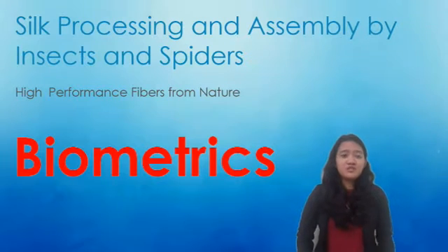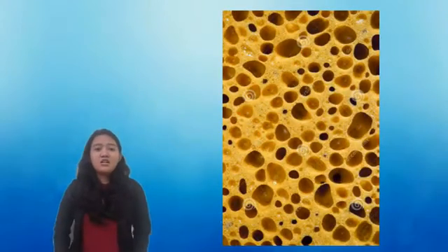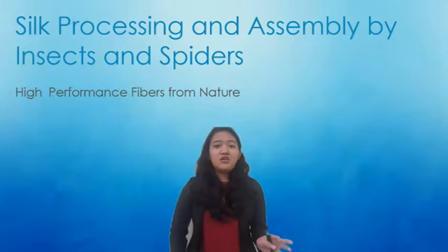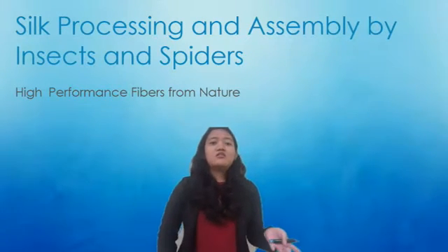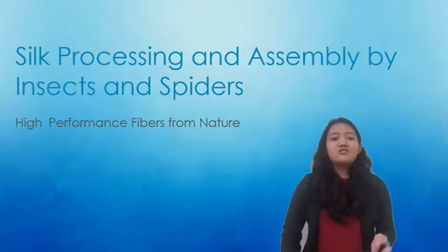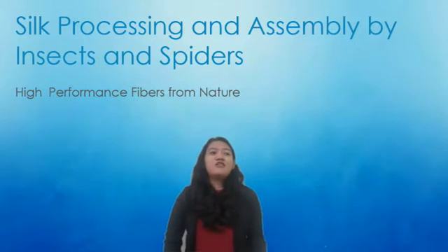Biomimetics involves the silk spinning process mimicked in vitro, for example, porous 3D sponges. Other approaches are blending silk fibroin and polyethylene oxide, silk protein assembly, and engineered liquid crystallinity. On the other hand, synthetic silk analogs are also developed in the laboratory, for example, copolymers of glycine alanine repeats with polyethylene glycol.